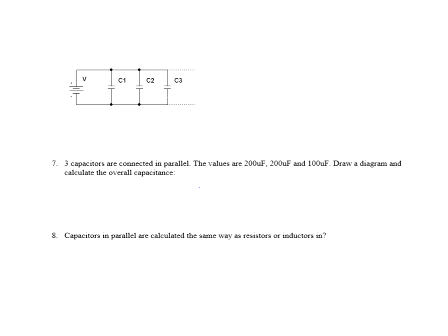Well, capacitors in parallel, you just add them together. What kind of resistors do you have to just add them together? Well, that would be series, wouldn't it? So capacitors in parallel are calculated the same way as resistors or inductors in series.